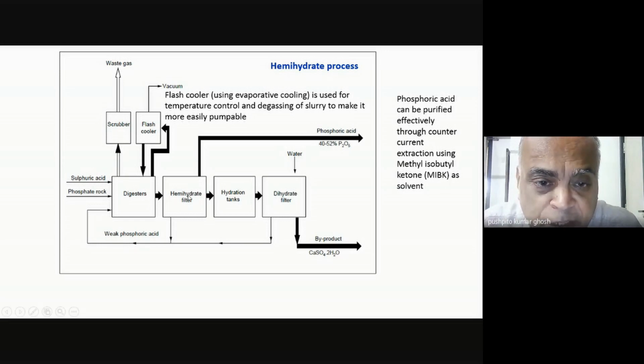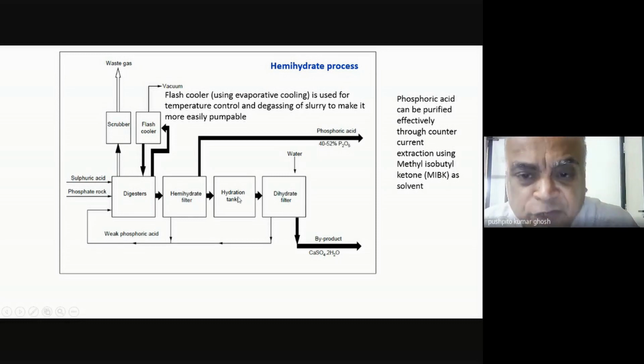So that's what they're doing. They're keeping it stable, and later on they're introducing hydration tanks where they're putting a very controlled amount of water and converting the CaSO4 half H2O into CaSO4 2H2O, and finally filtering.